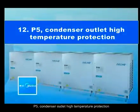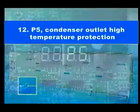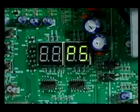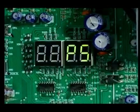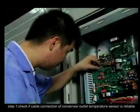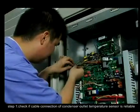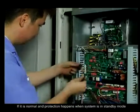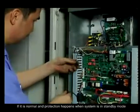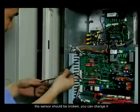P5. Condenser outlet high temperature protection. Repair instructions when P5 appears. Step 1. Check if the cable connection of the condenser outlet temperature sensor is reliable. If it is normal and protection happens when the system is in standby mode, the sensor should be broken. You can change it.